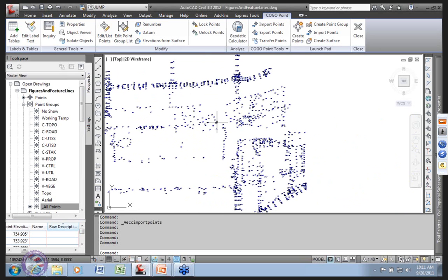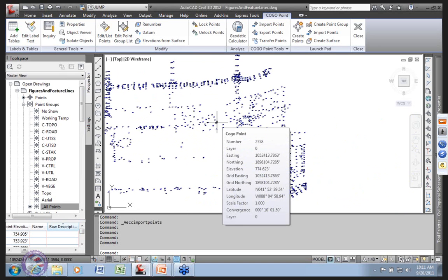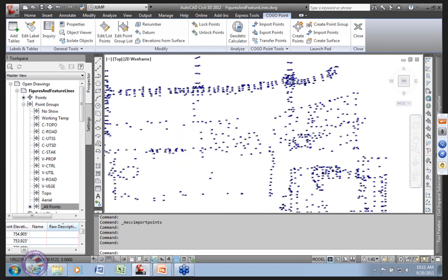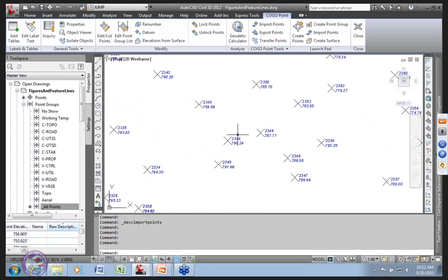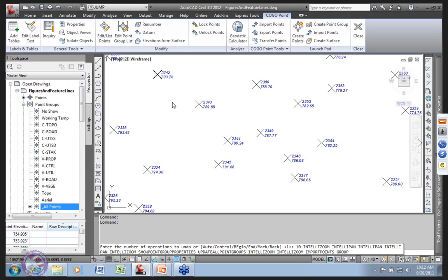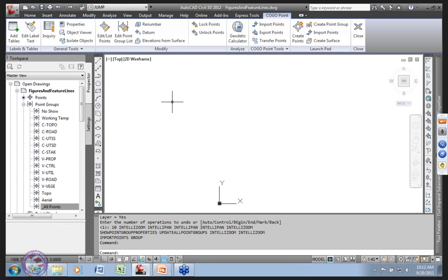I can immediately build the surface, so we could do that. We're going to just do a gross undo. So not having the descriptions means that pretty much now we're down to the simplest little point objects that we could possibly have, without much information happening. Just wanted to kind of review what's going on there. Okay, so let's go back to our import point event. Civil 3D is pretty graceful about removing all that stuff, not blowing up on you.